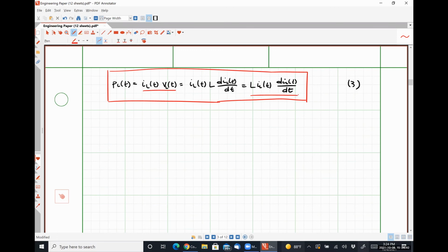I'm going to ask you what equation can be used to calculate the power in an inductor, or the power that is absorbed by a capacitor. And so for half of you, that is both of the answers that I have underlined, right? It's always going to be I times V, always, always, always. And then we can additionally express that as only a function of the inductor current, which may be useful.